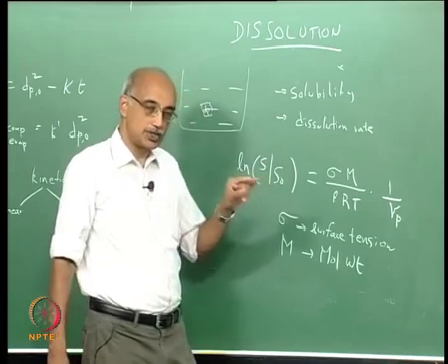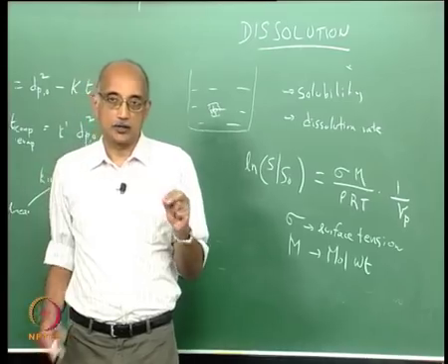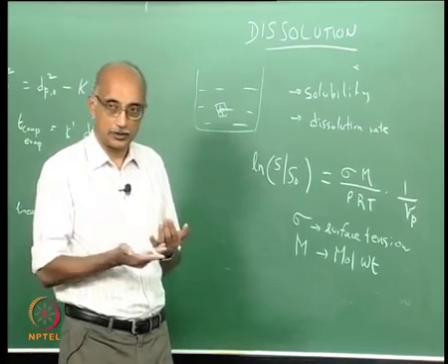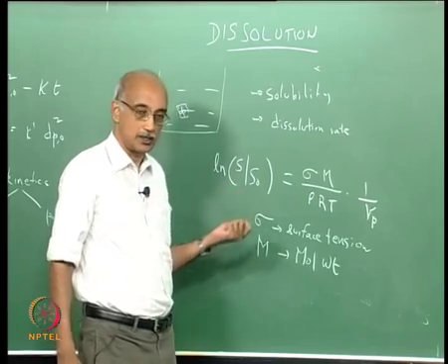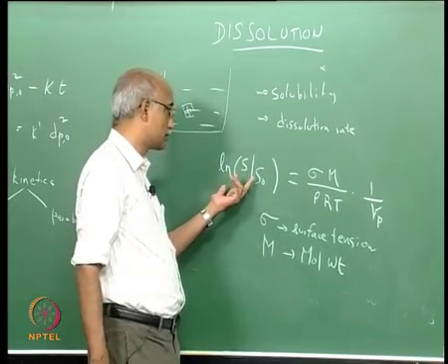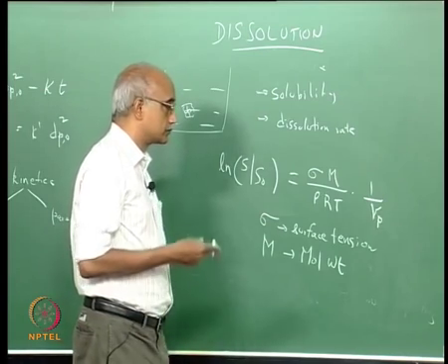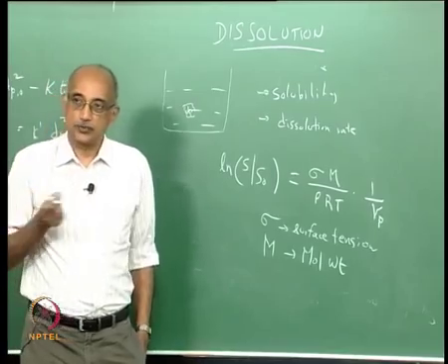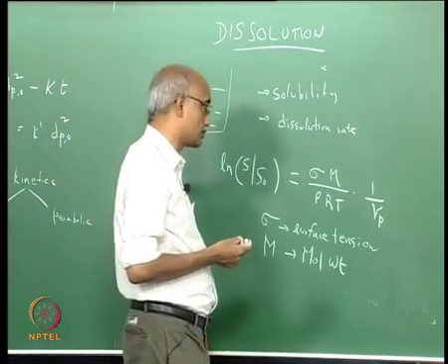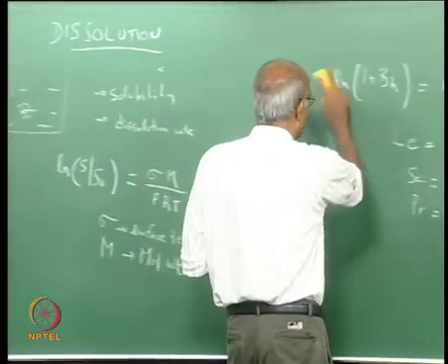This relates to the ratio between solubility of a particle to the solubility of a continuous layer or continuous substance. So, clearly the largest differentiator in this is the particle size. Now, this suggests that you should use fine particles if you want to improve the dissolution characteristics, but only from a maximum dissolution viewpoint.